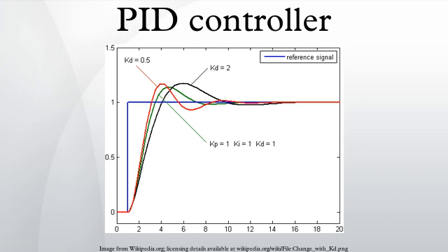Making a change that is too large when the error is small will lead to overshoot. If the controller were to repeatedly make changes that were too large and repeatedly overshoot the target, the output would oscillate around the set point in either a constant, growing, or decaying sinusoid. If the amplitude of the oscillations increase with time, the system is unstable. If they decrease, the system is stable. If the oscillations remain at a constant magnitude, the system is marginally stable. In the interest of achieving a gradual convergence to the desired temperature, the controller may damp the anticipated future oscillations by tempering its adjustments, or reducing the loop gain.